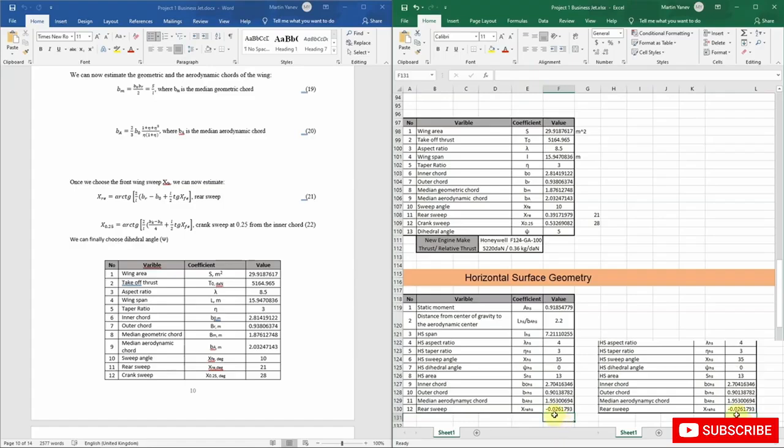And let's see what we're going to get. So as you can see here, we're getting a negative rear sweep. So we're getting a negative angle here. So in that case, we would need to change some parameters in order to have a positive sweep angle, which is always better. So as we cannot change the inner and the outer chord, we can either change the sweep angle here or some of the other parameters. But let's try to change the sweep angle. For example, if I do it like this, if it is 35.1, or even if I do it 36, then we're getting more and more sweep.